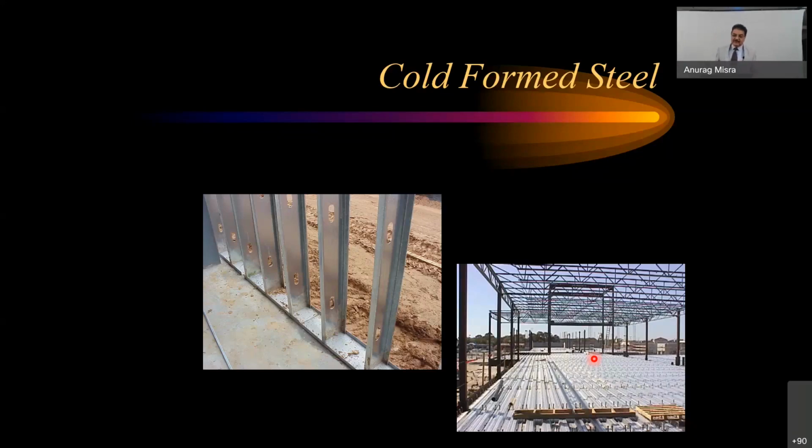So many times the shear stresses at that level would try creating a force which bond may not be sufficient for, because sheeting is reasonably smooth. So that is why we create indentation first. If that is not enough, we provide these shear connectors. So these are projecting and going into the concrete slab, and then this whole system is becoming rigid, and then this behaves as a composite section.